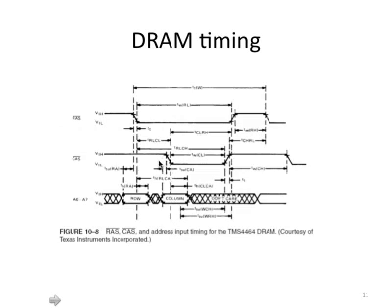The way it operates is that first you put the row address on this 8-bit address bus. And then you assert, which means you turn the row address strobe from 1 to 0 because it's active low. That's an indication that right now the value on the 8 address lines is the row address.